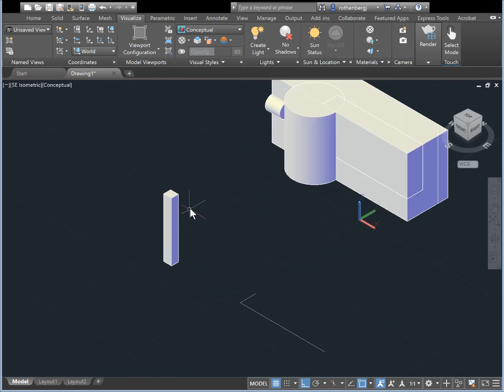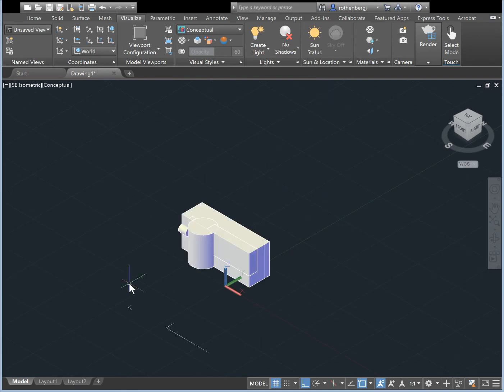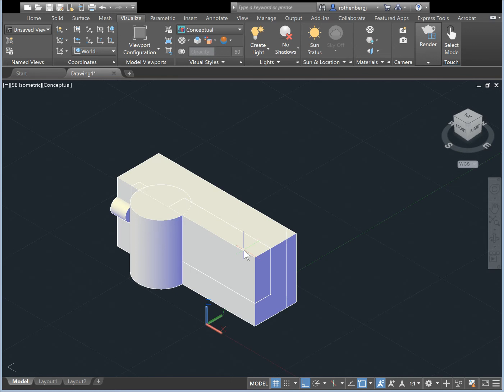So now our last piece. Now this rectangular prism is actually 15/32 from the left face. So we'll be drawing a line, except this time we could do it from the front left corner of it and over 15/32. Now select both, enter move, then select the endpoint not touching the rectangular prism, and once again move it to the front left corner. So now all of our 3D solids are moved in place. Now all we have to do is subtract them.